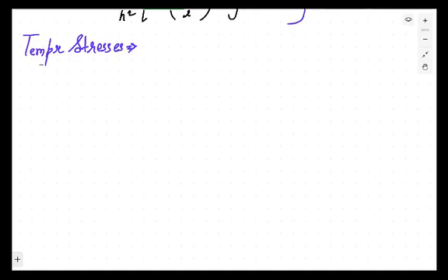As you have just studied, what is the critical portion for load stresses? The bottom portion of the slab. Why the bottom portion? The bottom portion is critical because the bottom portion has tensile stresses. That's why the critical portion is the bottom portion. Now let's talk about the temperature stresses. Let's consider a slab here.